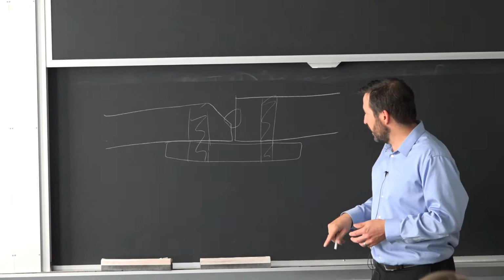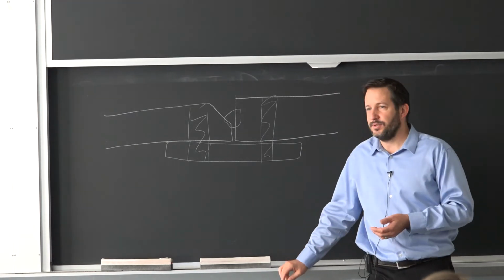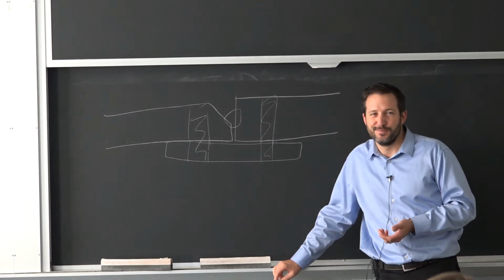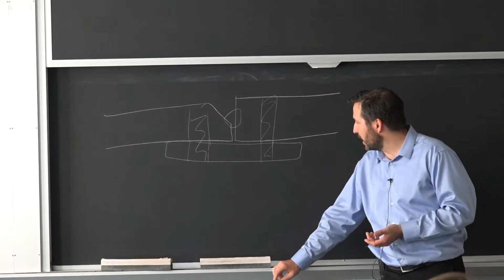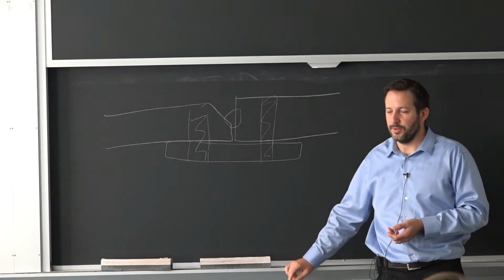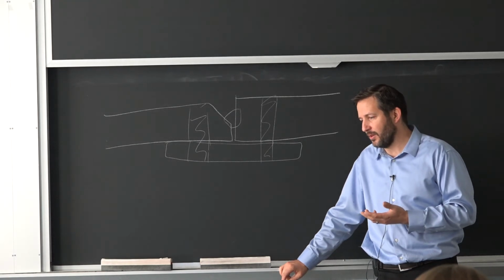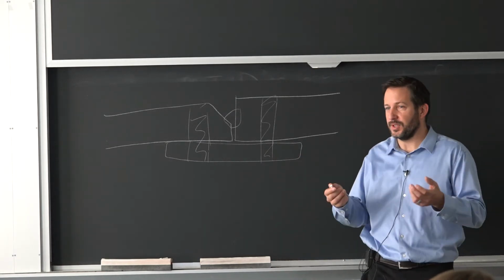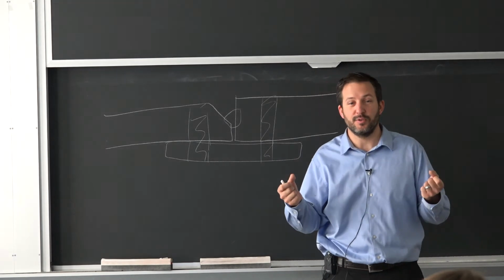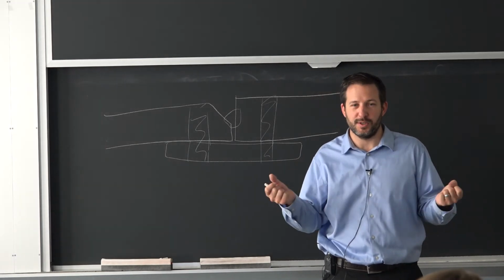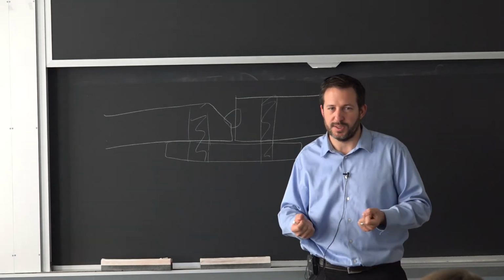So the only way that it's done on large structures is you do the hole in the field. Or you have the hole just on one side and you do the hole on the other side. But I hope you see it's just very difficult. And then when you tighten everything up, does it guarantee you that it's not going to move? Well, not really. You know, it can start sliding and move relative to the other.